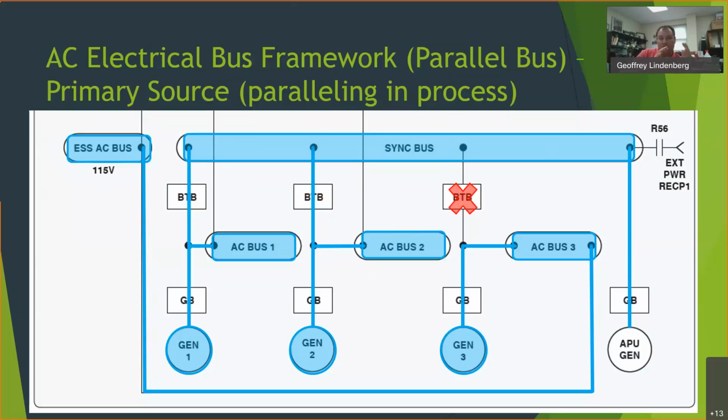And now what happens is when you have two generators that are connected together, they're close to being in phase, and you connect them together, electrically through electromagnetism, the electromotive force that's produced in the wires and in the windings in the generator, they actually lock in with one another. And so now they will spin, even if there's a slight difference in how fast they're spinning. That magnetic force will actually pull them in until they're in phase. So they'll spin at the same speed. They'll lock in voltages. They'll lock in frequencies, and the frequencies will be now in phase with each other instead of out of phase with one another.